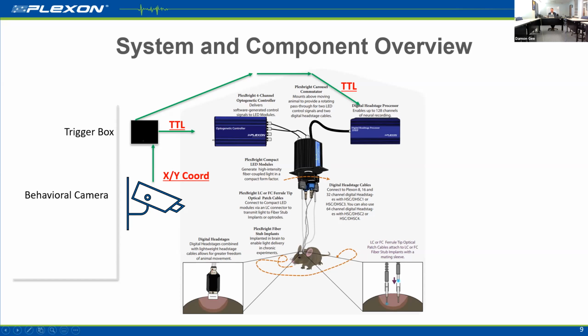We're going to be able to utilize our video tracking system along with the trigger box that Kristen mentioned to send TTL events, digital inputs, to trigger the onset of stimulation, the onset of that pattern generator that we've already defined, as well as sending TTL events to our Omniplex digital input board to annotate. This will allow us to annotate our neural recording with the times of stim onset, for example.